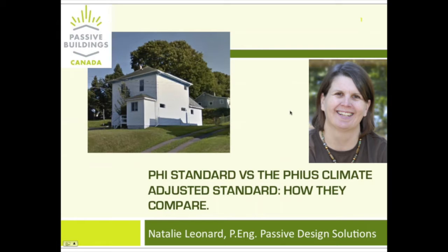We monitored the Hawkins passive house for about 2 years, and it definitely showed that the heat load was quite low in the house, and the electrical usage was higher than this house was certified to the PHI standard.